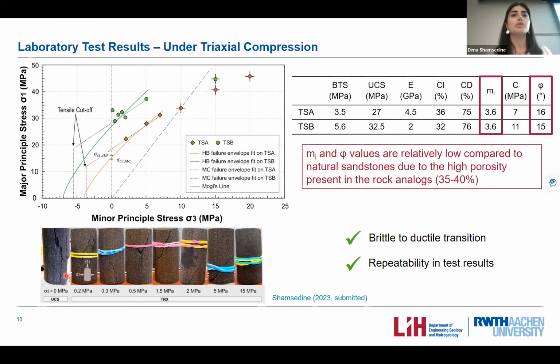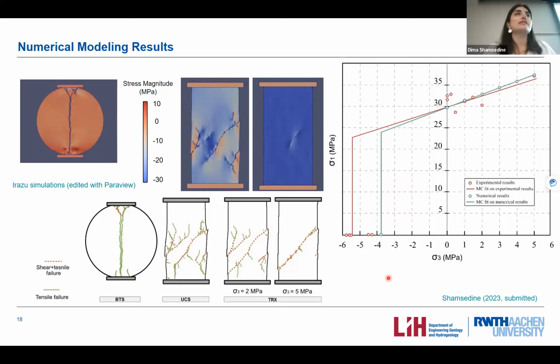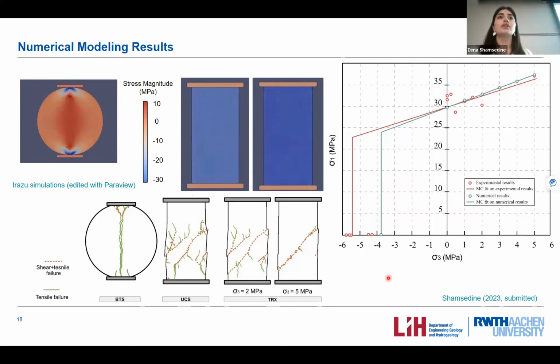So how does the porosity impact the model? Did you include the porosity of the model? No, the porosity is not explicitly included, it is just a solid rock. So the porosity in real life affects the strength and the elasticity of the sample, which are directly implemented in the input parameters of the rock, affecting the strength parameters and elastic parameters.